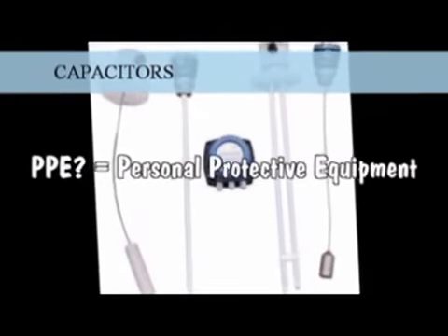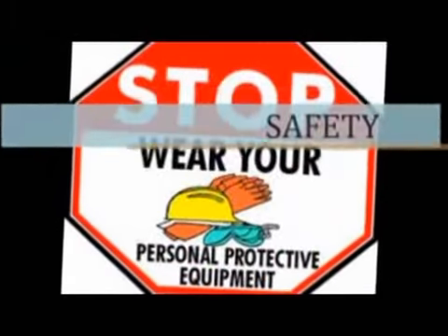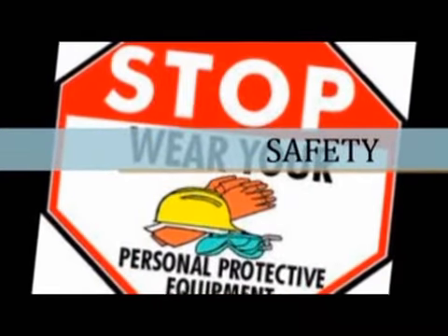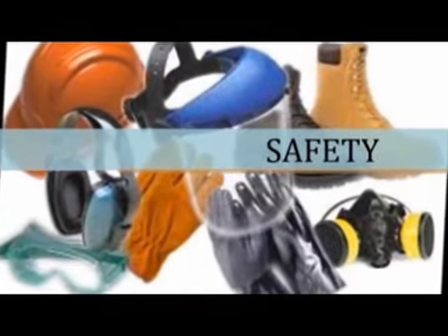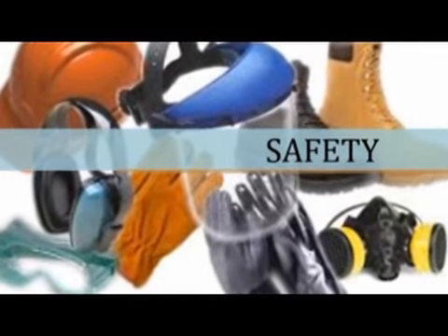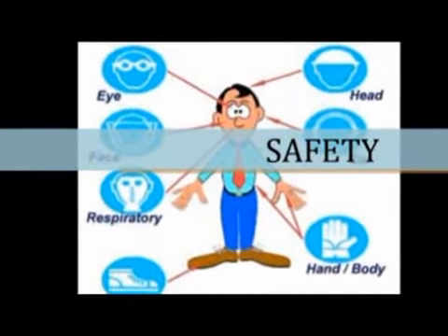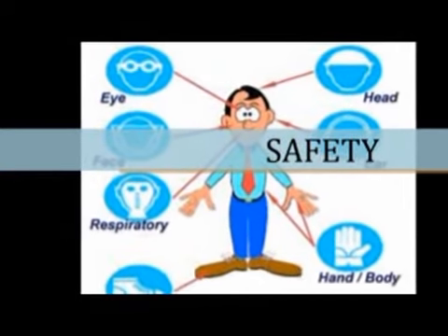PPE should be used whenever you could come into contact with exposed electrical parts. You must make sure electrical gloves and insulated tools are used. Next, you must wear non-conductive head protection. Last, all qualified electrical workers are required to wear electrical steel-toe boots at all times.